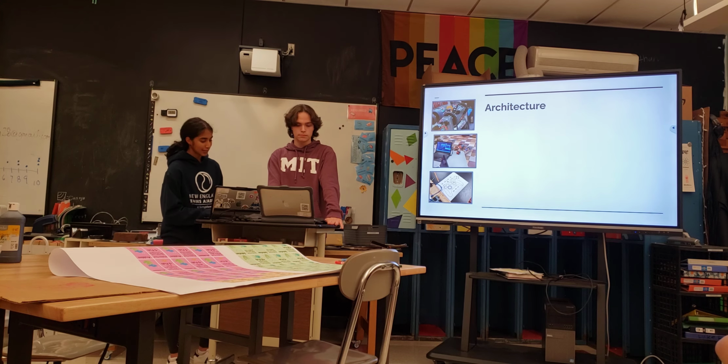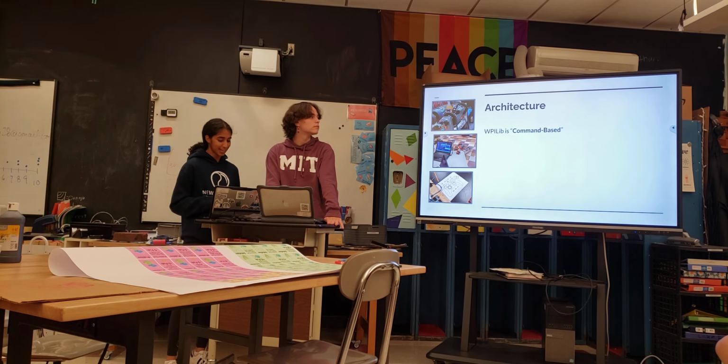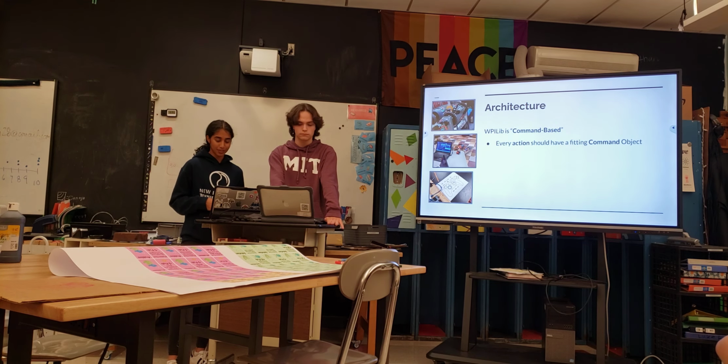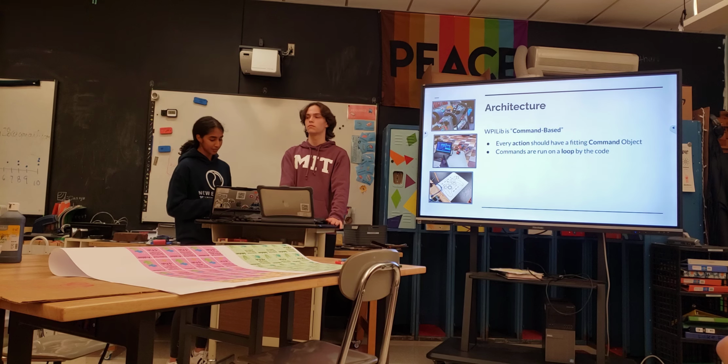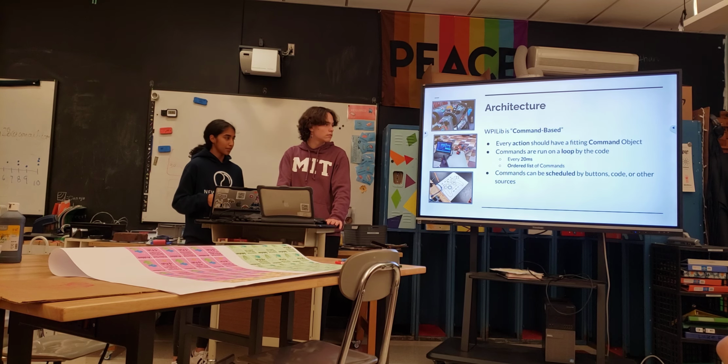Okay, so WPILib is a command-based structure. This means that every action for the robot should be defined by a relative command object within the code. These commands are then ordered and run every 20 milliseconds by an internal process called the command scheduler. Commands can be tied to triggers such as button presses from our controllers, or activated specifically within the code.